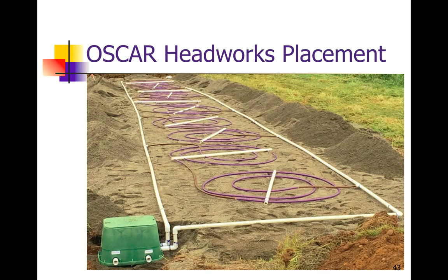If logistically you're not able to bury the box in the ground and you have to set it on the soil or on the surface of the ground, we suggest backfilling around that headworks with soil a good 12 to 18 inches and then finishing the backfill with sand. But again, we want to have soil or native material around that box for insulation.